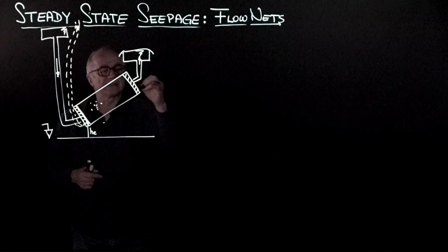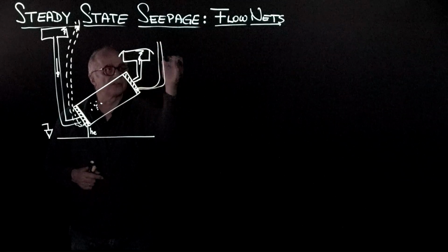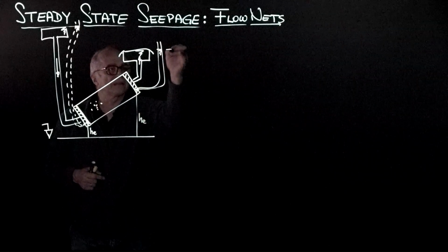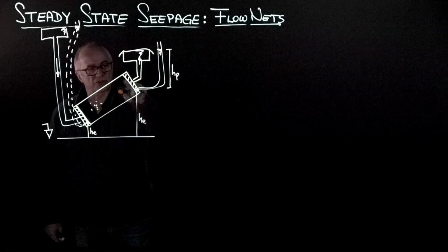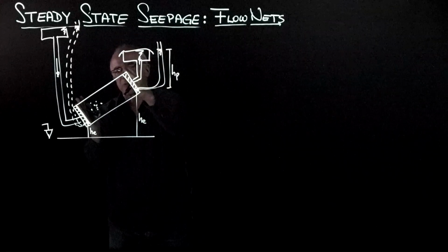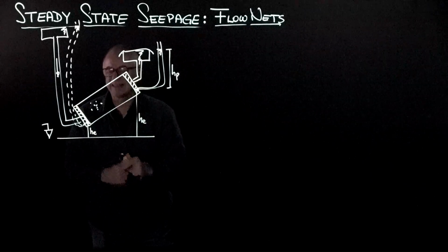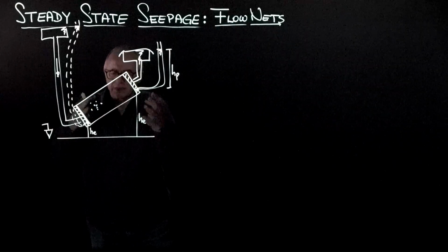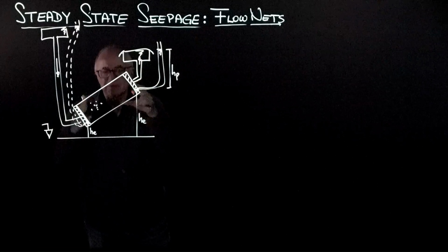And you can repeat the same, place a piezometer here, and it will go by communicating tubes to this elevation, and this is H elevation, and this is H piezometric head. And all across the boundary, it will remain constant. So these are my first and last equipotential, and these are the two extreme flow lines. It appears a very weird example, but there are geometric situations underneath structures that we may actually have something that looks like this.